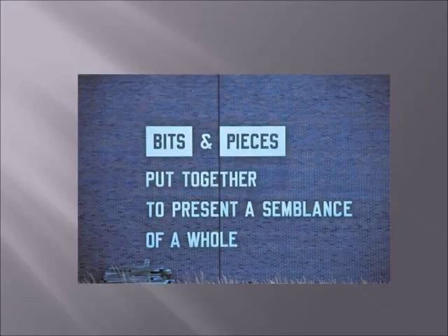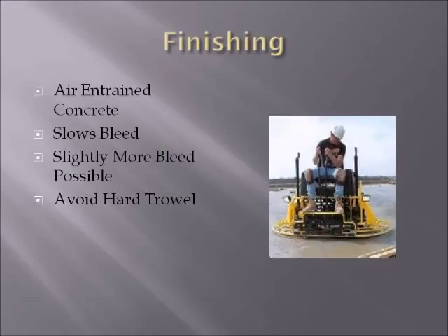And finally, a few bits and pieces I'd like to touch on, not necessarily related to economics, but they're topics that always come up with design engineers, contractors, finishers, people that we deal with every day in the market. Finishing structural lightweight concrete: structural lightweight concrete that you'll find in the field is almost always air entrained. That is to economize the mix and get the weight down as economically as possible. Air entrained concrete has specific recommendations and guidelines for the finishing process. You can find those in ACI 302.